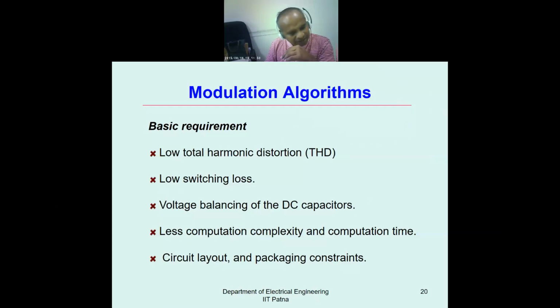Okay, so that way there is low switching loss and less complexity. I remember my guide gave me the task to design a sinusoidal PWM technique using only op-amps, and then a hysteresis current controller using op-amps. So I started designing, and when you design it, the circuit becomes so complicated. You require two comparators, then a lockout circuit, then the driver circuit.